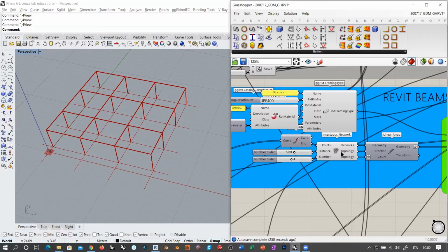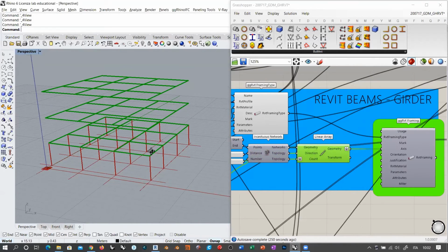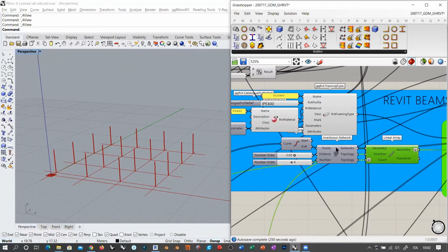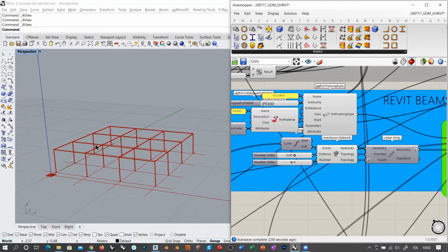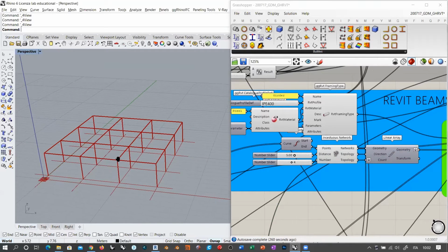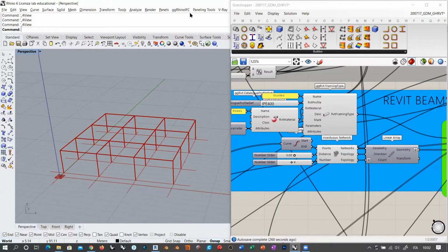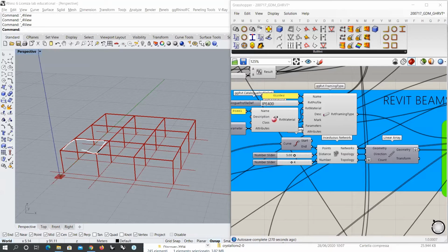Okay. Once you have the axes, I just repeat them again. And another reason for using this network is that you only have one line per connection. So if you imagine, for example, creating this set of connections using another method, for example, creating these polygons here, you will have 2 lines overlapping here, because this is one side for this polygon and one side for this polygon. So you will have 2 overlapping lines. And then you will have to use other tools in order to remove duplicate lines. For example, there are some tools in Kangaroo that allow to do this.